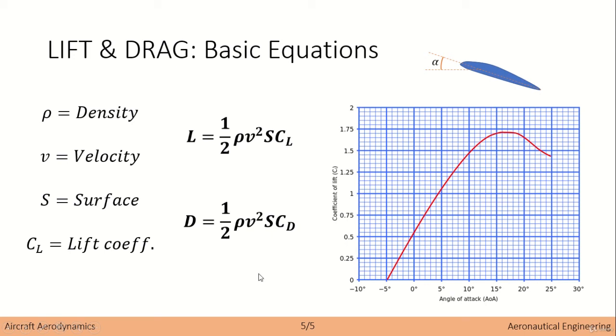What else? It's quite interesting to note that you may have seen that this curve is kind of linear. Not exactly linear, but kind of linear. From low degrees, minus 5 degrees for instance, to high degrees, 10, 12 degrees, is kind of acceptable. With more degrees, you're probably going to have problems, because this part over here is known as stall.